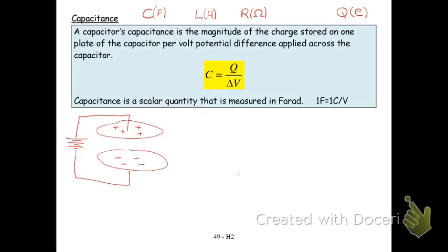Yes. So, very good. So what you're doing is you're using the radio frequency of the station as your driving frequency, and you're setting up the natural frequency of your circuit by using the capacitor and the inductor. And when the driving frequency matches the resonance circuit, that matches the circuit of your radio, you get resonance in that circuit, and so the signal is amplified. So you use an amplifier after that to make it bigger.